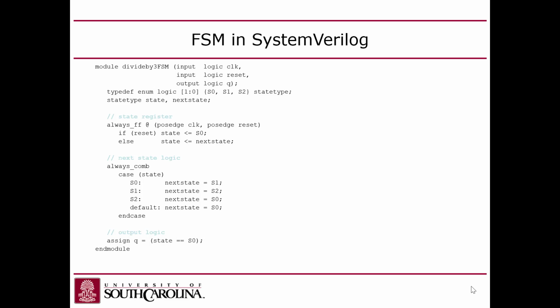And then they have a state register section. So there's 3 parts. In Verilog, we used to call this the clocked process. In this case, they call it the state register, meaning that you have one always block that has a clock. And then you have 2, the next state logic and the output logic, that are combinational logic, which in Verilog would be always comb, or a continuous assignment statement, an assign statement.